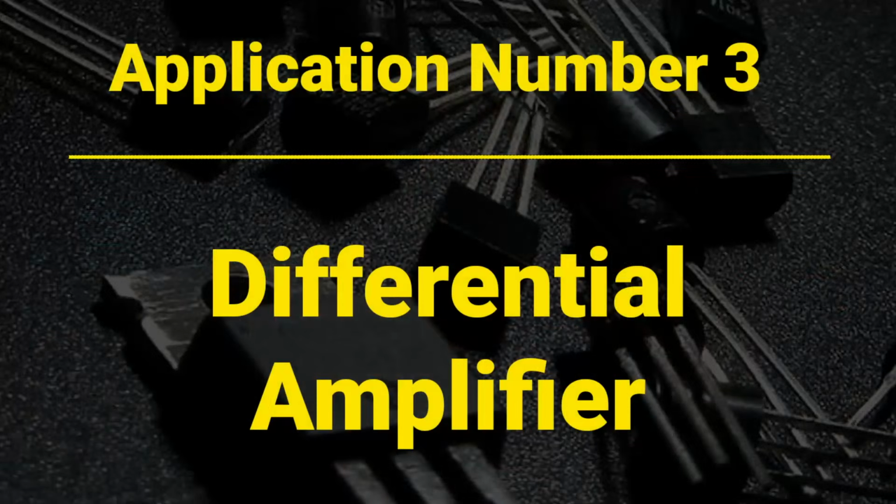Application number 3, using op-amp as a differential amplifier. The differential amplifier is a configuration of an op-amp that takes two voltages, multiplies the difference between them by the gain and puts the result on output. A non-inverting amplifier amplifies a voltage that is relative to ground, but the differential amplifier amplifies the first voltage relative to the second. We will see what it is good for.